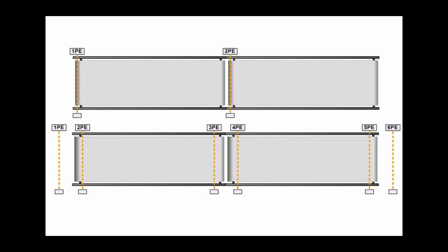However, if you want to move cartons from A to B and save energy, you need photo eyes to sense when there is something to move from A to B, thus not running the conveyor motors continuously. If you want to know how many cartons are on the conveyors, you need a sensor for an event to count up when they arrive and a sensor for an event to count down when they depart.